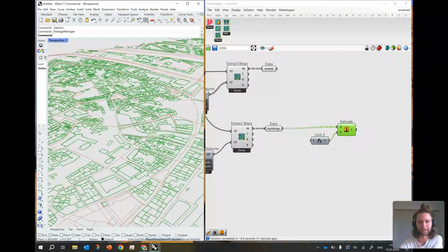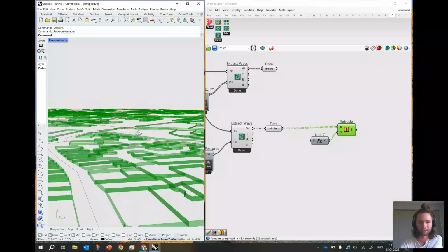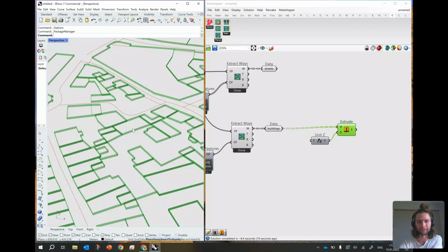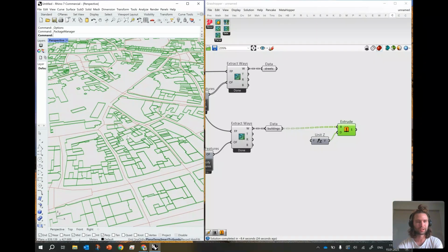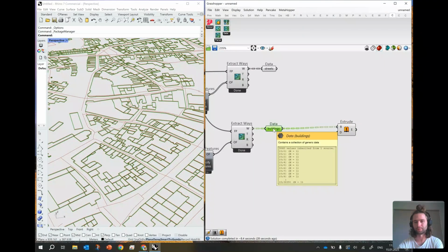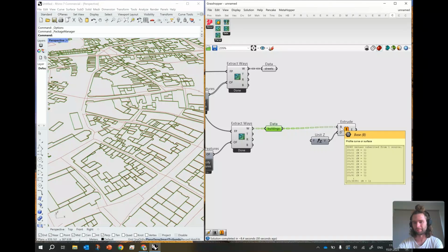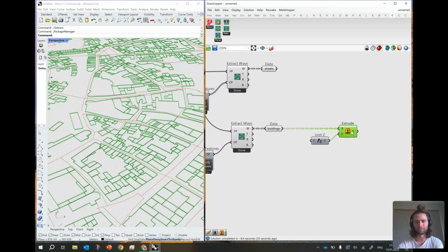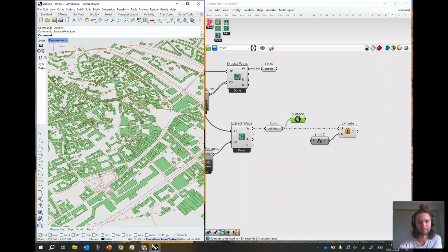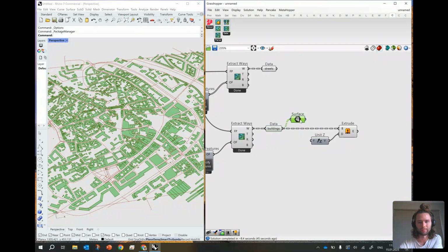Also you see now all the buildings are simply extruded by a height of 1 meter, but we don't see the roofs here. I want to cover my buildings with flat roofs for now, and I don't see them. This is because I use polylines instead of surfaces to extrude them. So one thing I could do is convert my polylines into surfaces and extrude surfaces. And I think it is actually the preferred way, which I will choose.